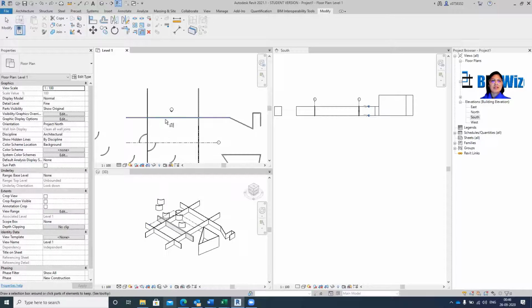Extend, I would select the wall. I want to keep this side, I select this side, I select this side. So these are commands I would really want you to play with, all of them. Draw, I will give you exercise files and I will also email you what you have to do in that.